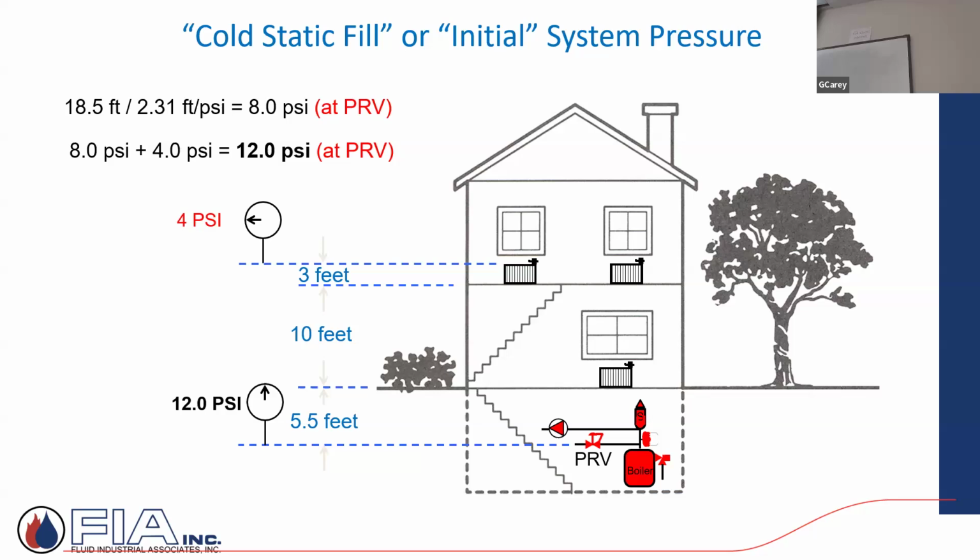The other benefit of sometimes putting that mechanical equipment up at that high point is, what's the pressure on the relief valve at that high point equipment? Back to your 12, 8, whatever you set it for. Versus you take that and bring it downstairs, and all of a sudden you get all the weight of the system sitting on the relief valve. So now you're looking for much higher rated equipment, relief valve ratings on the boilers, and bigger expansion tanks and all that. So just things to be aware of, that static pressure and what it can do.